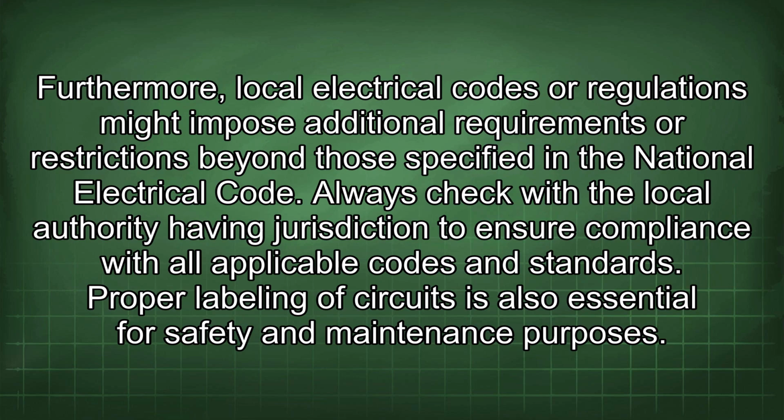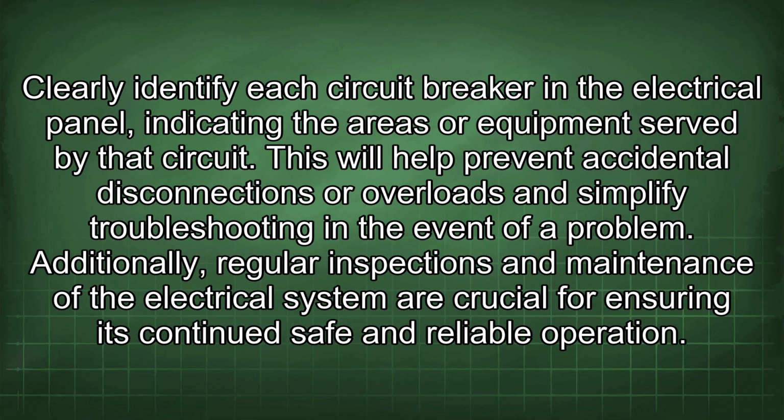Proper labeling of circuits is also essential for safety and maintenance purposes. Clearly identify each circuit breaker in the electrical panel, indicating the areas or equipment served by that circuit. This will help prevent accidental disconnections or overloads and simplify troubleshooting in the event of a problem.